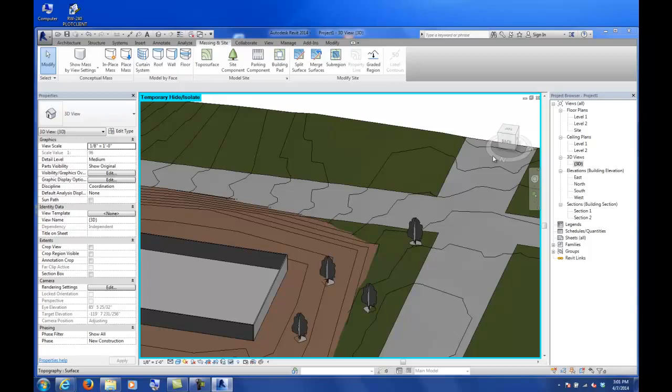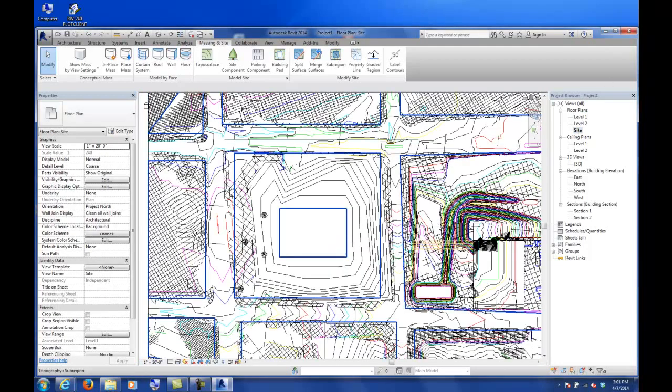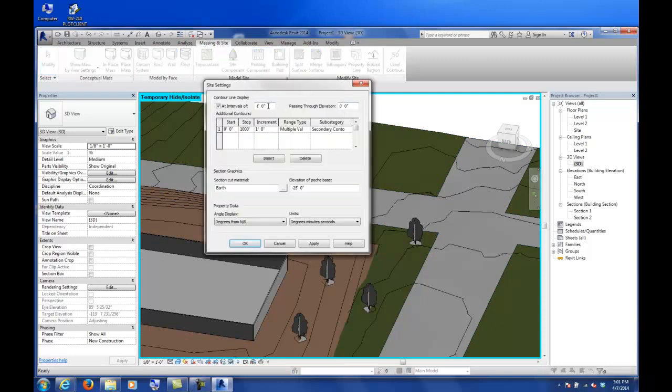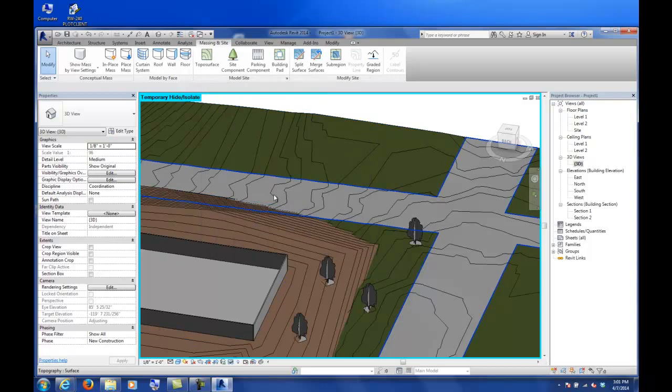You'd want to start picking points and make your sidewalk at different intervals along your contours, because then it will show, as long as it's a true topography surface. When you look at it in your plan view, or even in 3D, it'll generate contours for you on that surface, and those contours are based on these settings. I could also make this more detailed, make it 6-inch contours, and you can see I got some added contours in there.